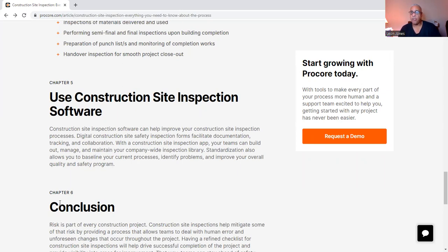When you're doing a building project, you're going to run a DCP to make sure that you have strong soil so you can lay a footing. And to make sure that when a contractor is using an auger to drill caissons, there's no water down there in that place, because when you do a caisson, they could go 10, 20, 30, or 40 feet down, and then they got to put a rebar cage in there, but you have to make sure that there's no water in it, because water, once it gets on concrete, when concrete is placed, it weakens the concrete.